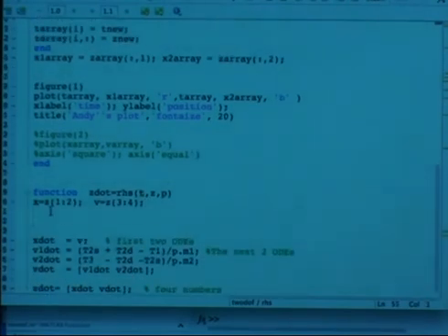Okay, so what are these T's? Well, T1, which was the first tension, which was pulling the first thing back, was equal to K1, which I'm going to say p dot K1, times X1, and that's X1 like this, or I could have made a new variable called X1, which was X sub 1, minus X0, which means I've got to calculate what X0 is. And then I have minus the initial length of that, which was p dot L0. And L is an unfortunate variable because it's hard to keep it straight from 1, which looks like that.